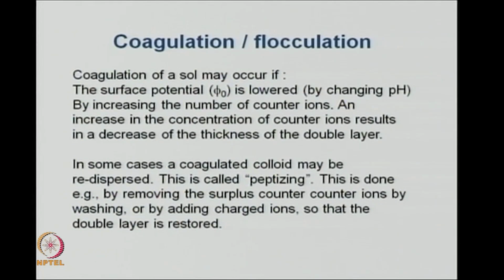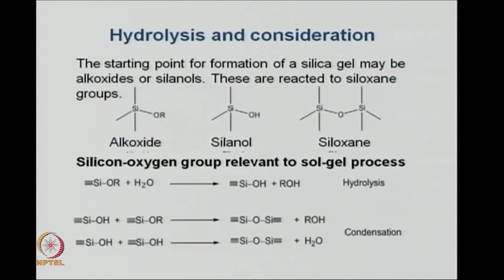This kind of process is very important in industries. Most of the pharmaceutical industries, oil industries, etc., use these techniques of coagulation and flocculation. It is also important in our course here, where we are discussing how to synthesize monodispersed nanoparticles using the sol gel method, that is, to control the size of the particle from the sol to the gel using various charges or pH around the ions.